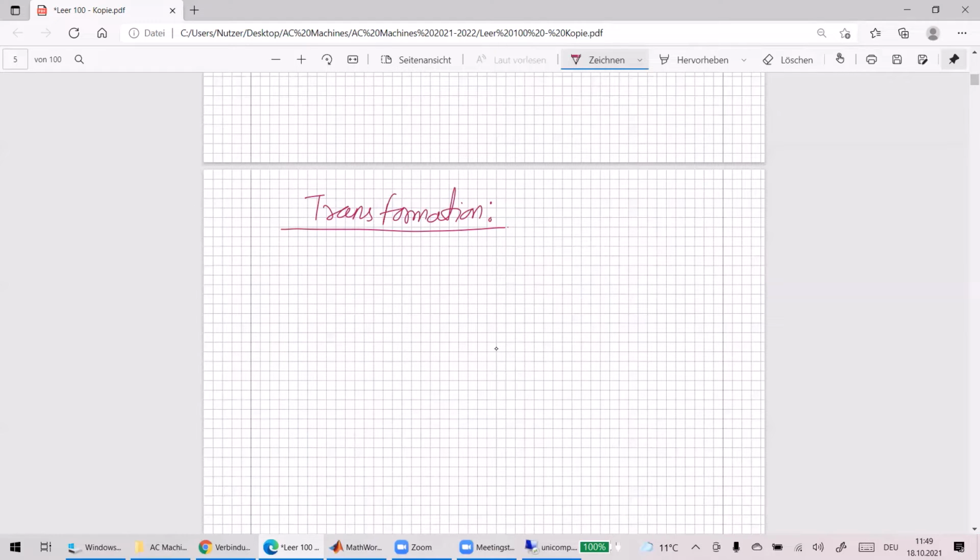Let's say you want to connect your converter to the three-phase grid. You have to synchronize first, right? And for synchronization, you need to make sure your converter produces exactly the same voltage as the grid. Only then can you close your contactors and connect to the grid. Otherwise, you cannot just give any random voltage and connect to the grid. You may burn the whole system. So you have to take care of your magnitude, your phase, and your angular speed also.